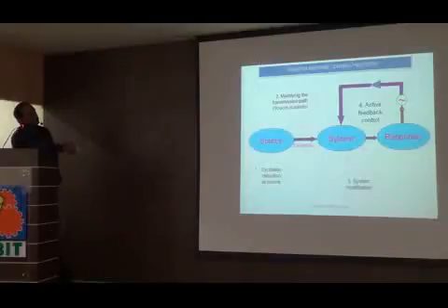The other option is you try to modify the system, means try to reduce the system frequencies or increase the frequencies, change the mass or stiffness matrix or the dynamic matrix, and then you reduce the response. Most of the time this may not be possible for us also. So either we have to depend on modifying the source or this. We will see some cases where we modify the system, where we change the transmission path. This is not possible for us.